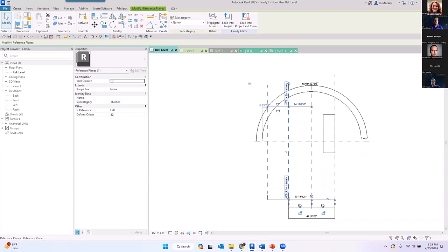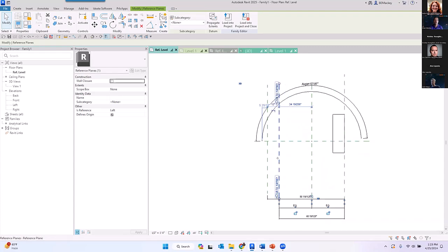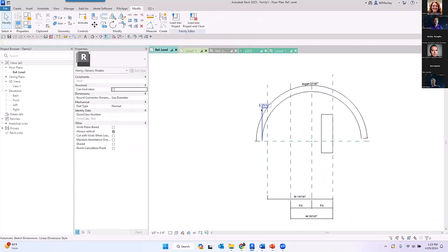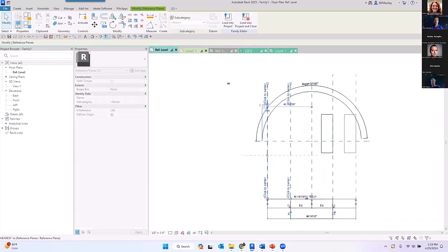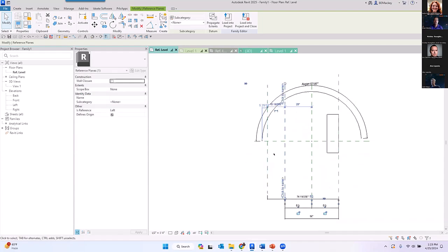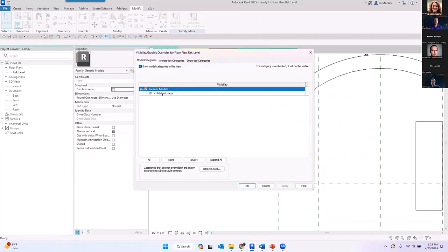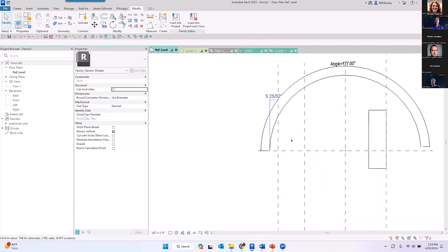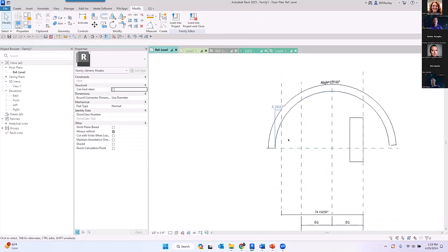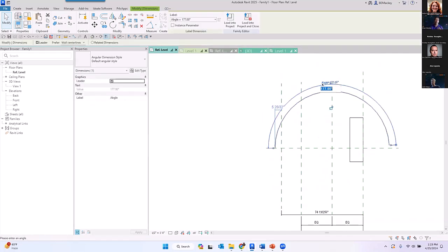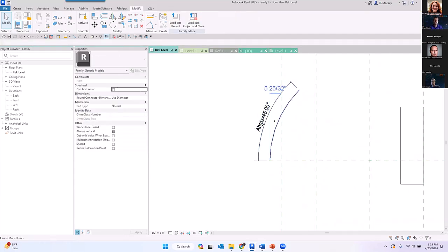And you're like, but when this was moving, that was moving with it, and now it's not. I manually did this, but Revit sometimes will start automatically doing this for you, especially if it's something like, oh, cool, I put that on top of that, and then I moved it. One day Revit might be like, oh, I'm going to reassociate myself to that other object. So turning on the automatic sketch dimensions in your families lets you see, do I have any of these blue dimensions? If I do, I haven't constrained this family properly, at least in my opinion, because Revit's got this automatic associativity built into it.